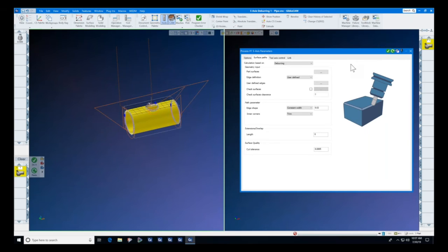Well, and I would expand on that, Patrick, a little bit to say that the multi-axis package, as you noted, can support 3, 4, and 5 axis. And a lot of people are starting to realize that you can use the machining strategies in the multi-axis package for non-5-axis parts or non-5-axis features. And there's a lot of advantages to that. So for example, better tool life, better machining strategies, even for non-4 or 5-axis parts or features. And deburring is just one of those advantages. Yes, exactly.